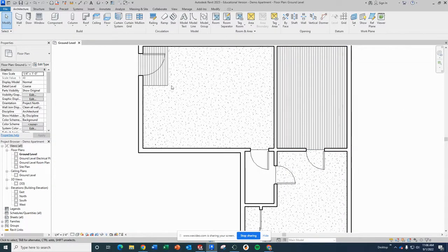All right, the last thing we're going to do to allow for movement throughout the house is the wall opening. Under the architecture menu, in openings, there are several different openings right here. We're going to create a wall opening. The wall opening is probably the easiest tool to use. Once I create a wall opening, I click which wall I want to open, which is this one. I click once, click a second time to pick a start position, and a third time to pick an end position. And as you can see, I now have an opening in my wall.